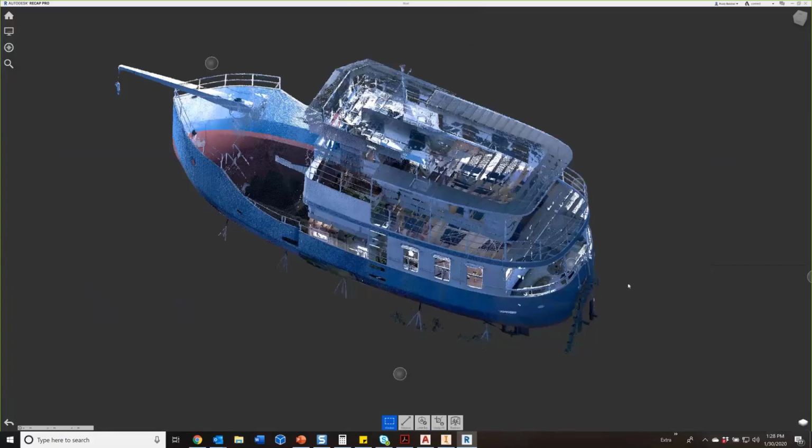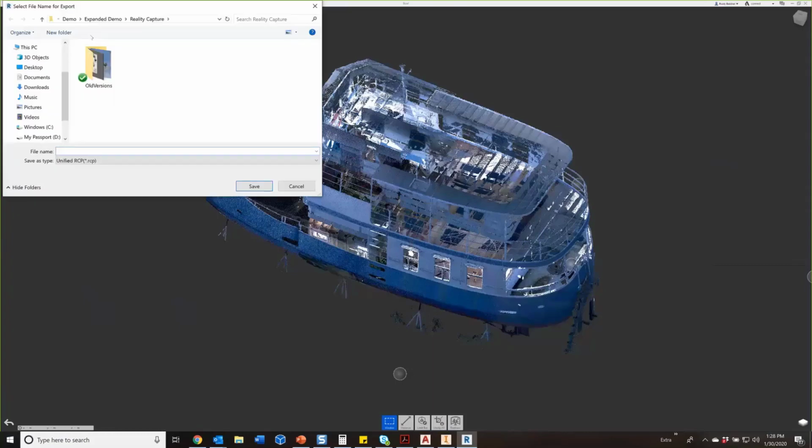So once you have the scan clean, we focus a lot on exporting it. When you go to export your scan, you've got a couple of things to think about, a couple of file types that you have options for. You could export the project file as it is. Typically I don't export and create new project files. That's an RCP. If the scan is good the way it is right now, you could use it as it is. Just insert the RCP into Inventor.